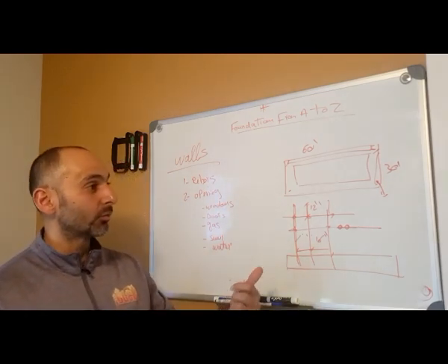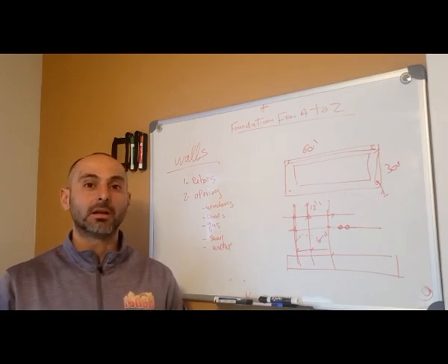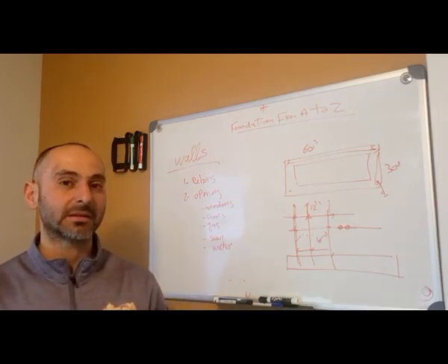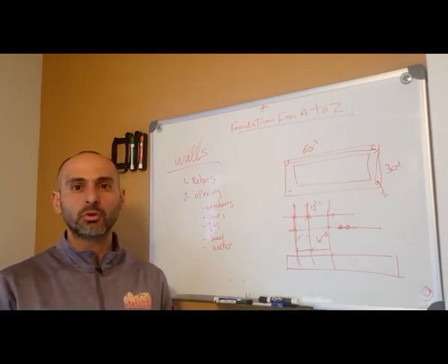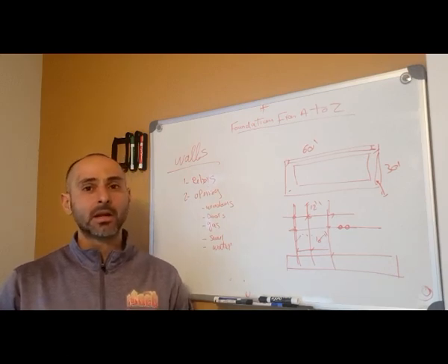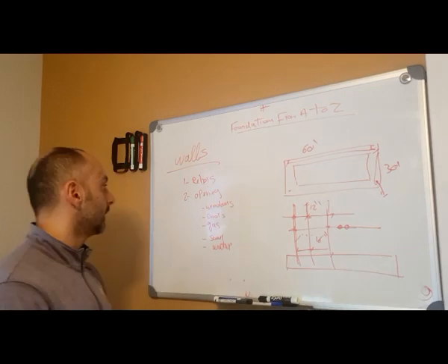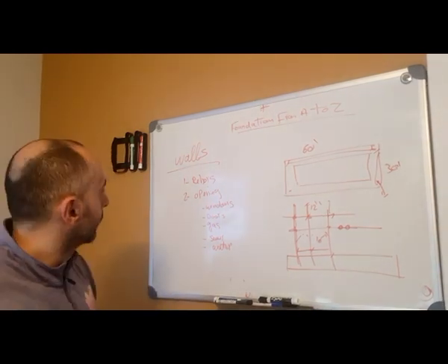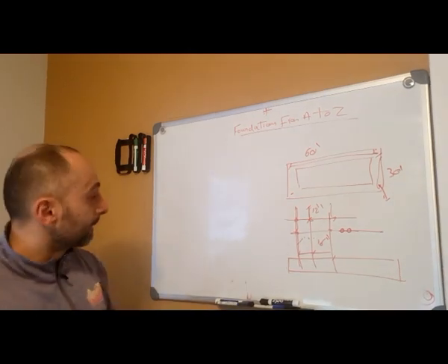So when you bore walls, check that it's usually 4500 PSI or 4000 PSI, so it's very hard for water to get through. Also, we do waterproofing on the outside, so you put these two things together and in no way is the water going to get through. Now after you do the walls, you're going to do the slab.